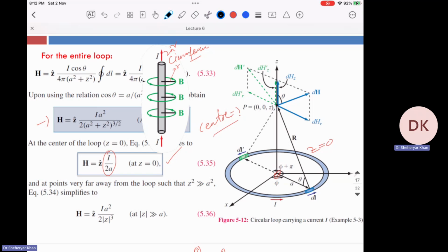So you will study electrical machines in a different subject that will teach you how machines can be built, but the phenomena and principles that electrical machines use are based on the principles that I'm teaching. B equals mu naught I over 2 pi r is the fourth basic principle. You provide a current and then you get a magnetic field. Now you use that magnetic field for electrodynamic purposes.